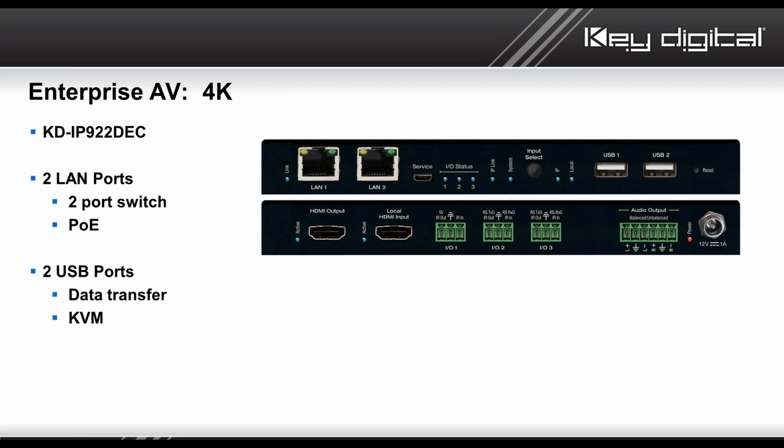Imagine you have a video wall, 2x2, 3x3, larger, as we discussed earlier. It could go all the way up to 10x10. You can actually cascade the LAN ports as long as it's the same video source. So if your video wall is all showing one large image, that's fine. At 4K or at 1080p, you could actually have 4 unique video streams. I want to say 4 unique video streams. We'll have to please double check that with our system design group. And then you do have 2 USB-A ports as well, as described earlier.